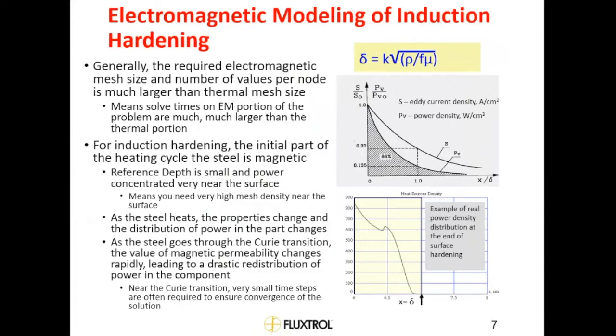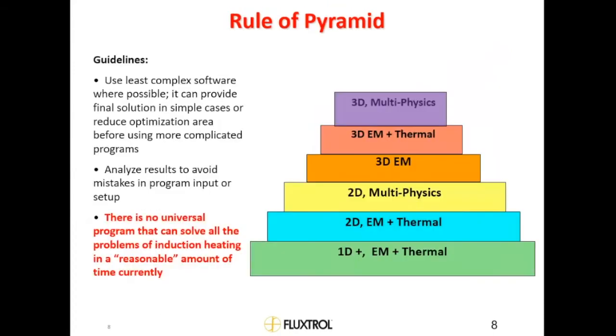And to get it to converge on the proper temperature result, a lot of times you need a very fine time step and a lot of interim calculations in the solutions. This means that the induction process tends to be longer to model and require more elements and more real values and imaginary values than other heating technologies. So based on that,